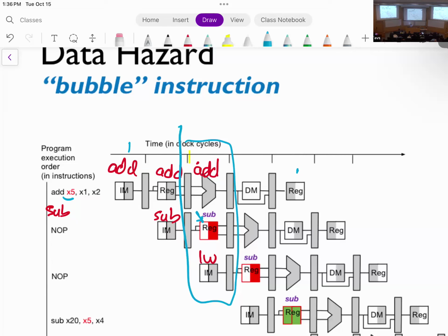So what I'm going to do is prevent this register file, this register here, from getting updated, okay? So I prevent the sub from moving forward. This is what we call stalling the processor. So stall the decode stage from advancing to the later stage of the pipeline, okay? But I don't stall the add because I want the add to reach this stage here, okay? So I'm going to let the add continue. So add is going to continue regularly, but my sub can no longer go forward.